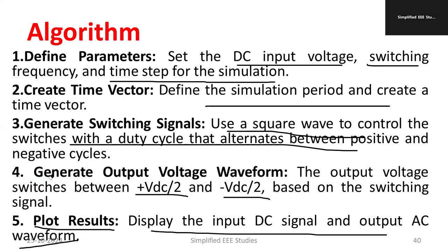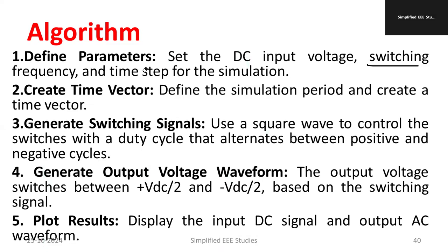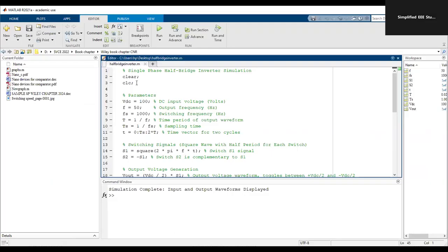Now I am going to show you how to develop the same in MATLAB. First of all, open MATLAB by double clicking the MATLAB icon. Thereafter, go to the command window and type edit, and the editor file will appear. The editor file will look like this. So we can type the code, as many lines as you want.